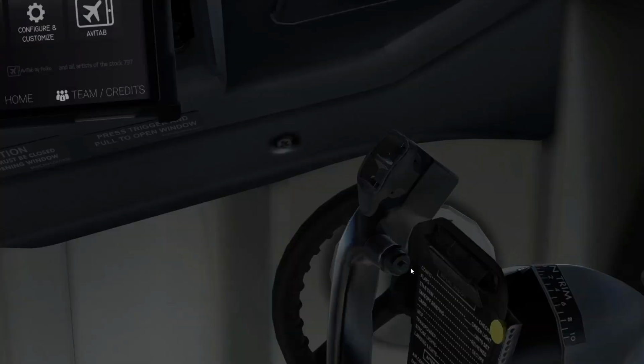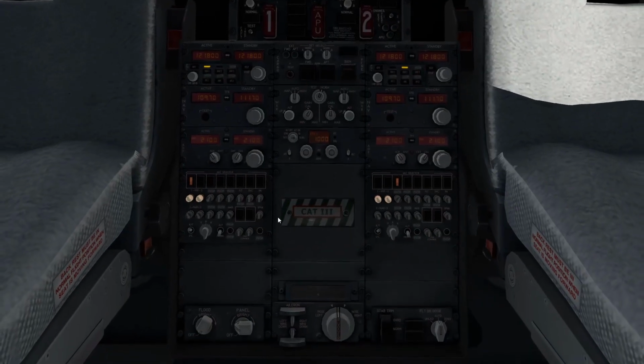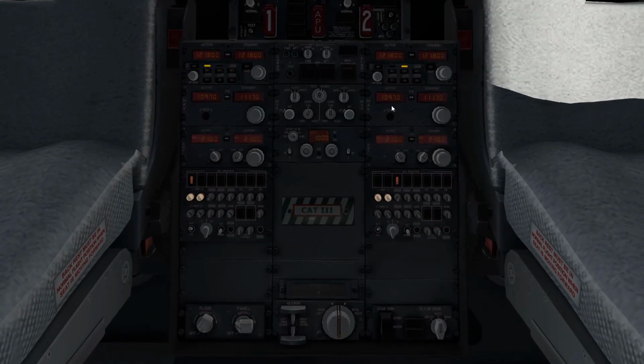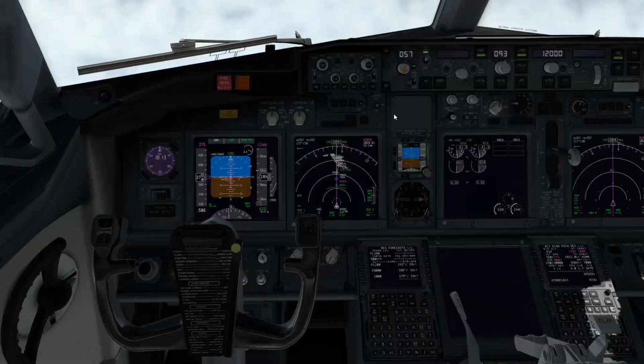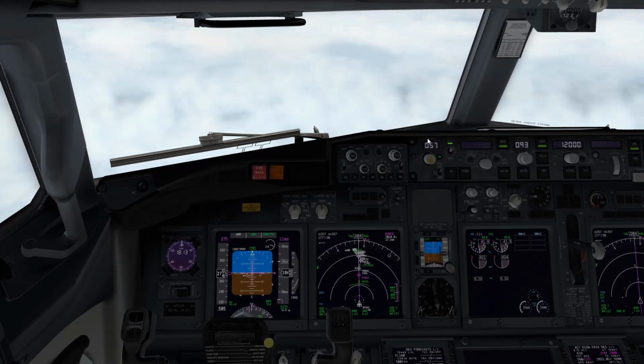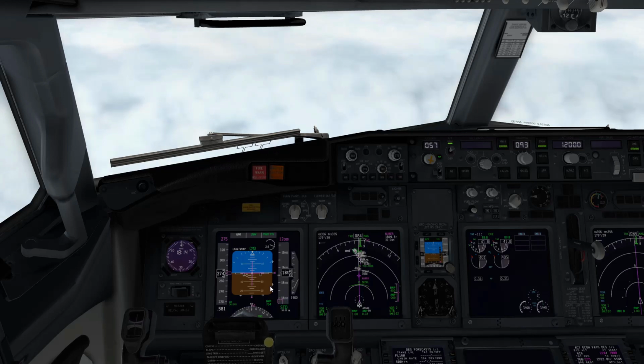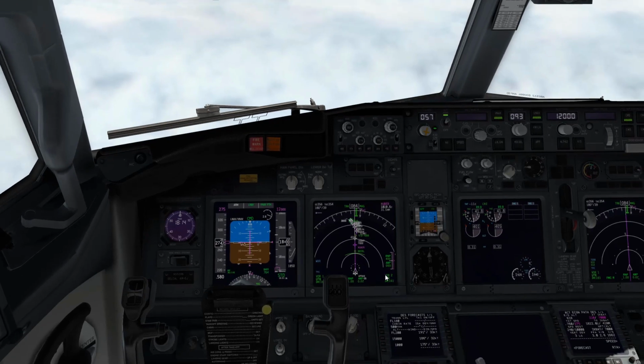Next thing I do is, sorry, pushing all the buttons here, I verify 109.7 is in our nav radios, and back up here, course 057, and minimums, barometric minimums are set. Looks like the aircraft's following the path nicely, and we're pretty much on our planned speed there.